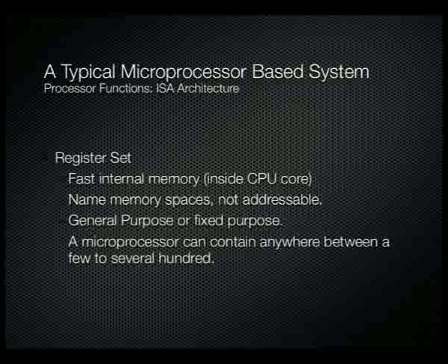Okay, a register set, effectively it is named memory. It's not addressable. You can't say, okay, I want memory address 0 and that's your particular register. No, they are named. And by named, I mean there are a series of instructions that operate purely on that particular register. So to go back to the example I gave you before of load accumulator A, that effectively defines the register accumulator A. So the instructions in fact name the particular register that they want to operate on.